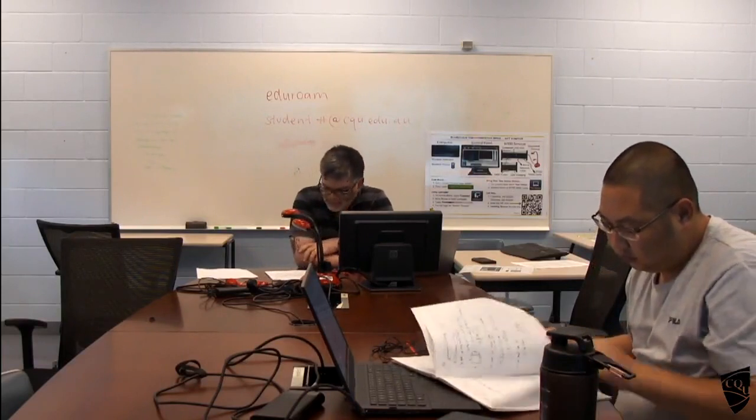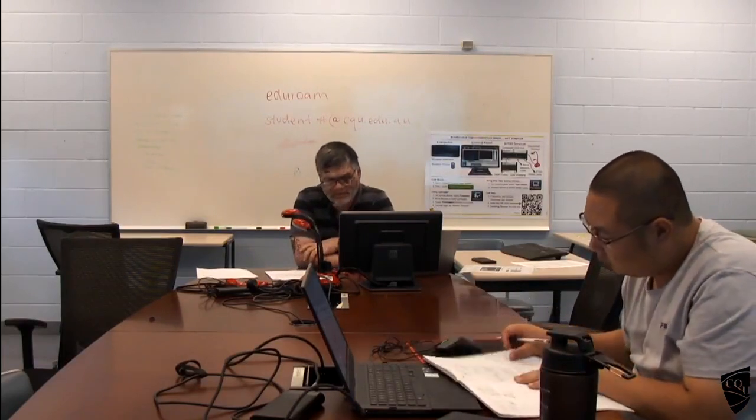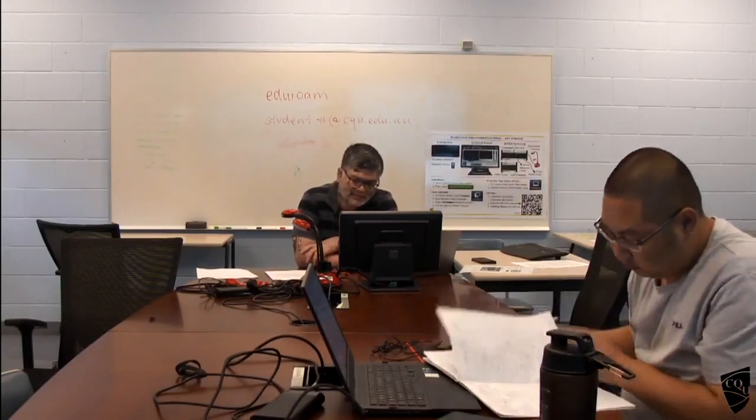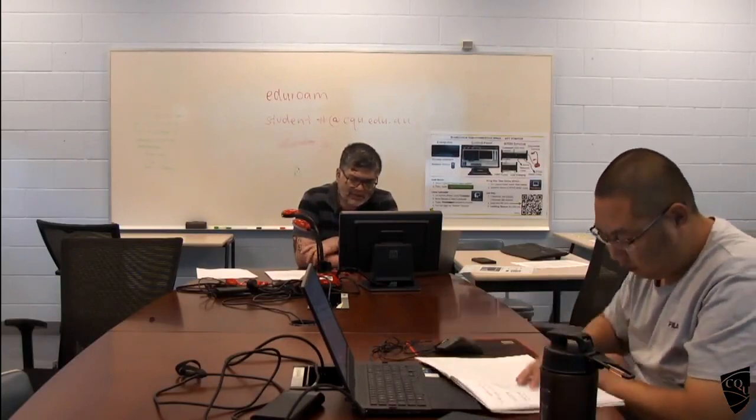The superimposed dead loads may be from 0.3 to 1 kilopascal generally, if you look at the ceilings and the services. But if you have tiles and other things, it may be a little bit up.